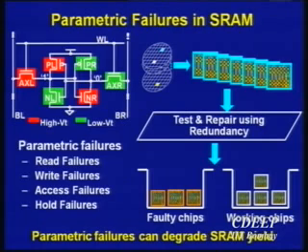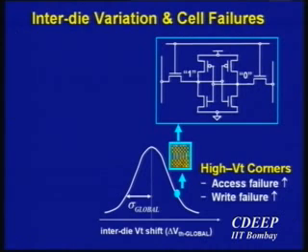So the interesting thing to look at is that after all those sort of things, redundancy, repair, and so on, you're going to have a number of chips which are working and a number of chips which are faulty, right? Unless you do something. What we did also is we did an analysis of 45 nanometer SRAM, 64K SRAM, and did extensive simulations of it just to show how bad the problem can really be.